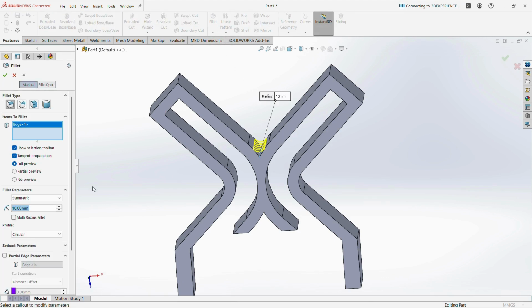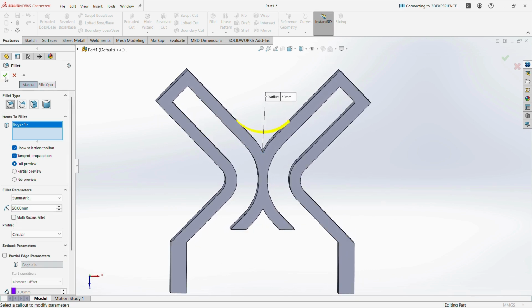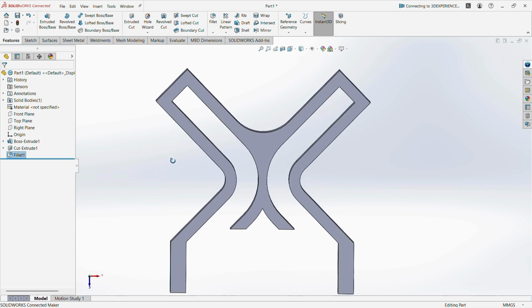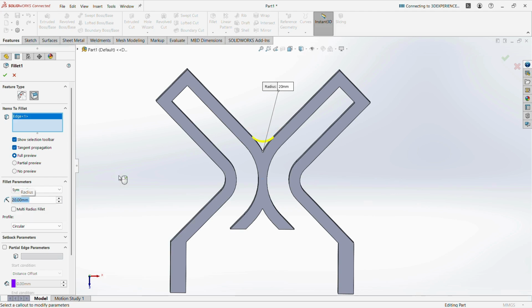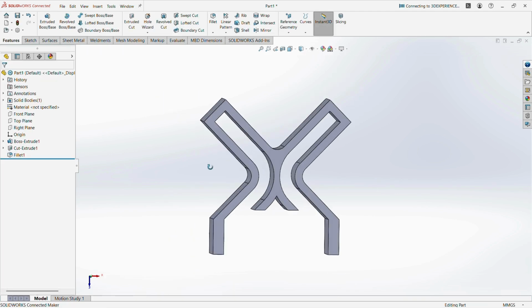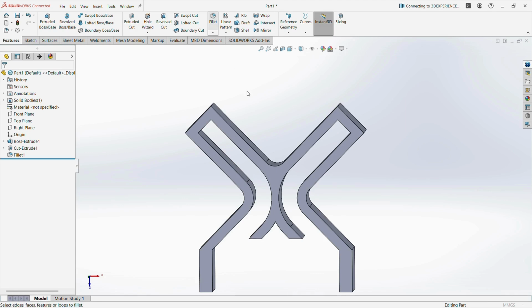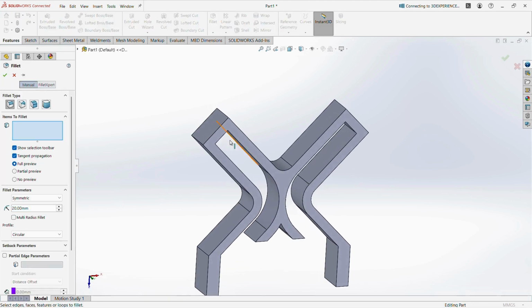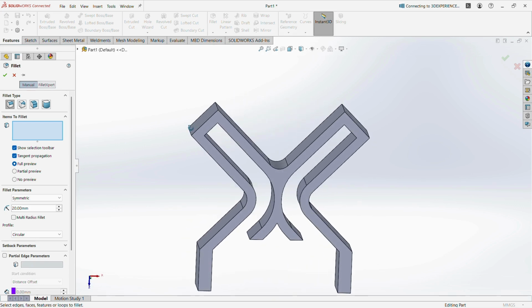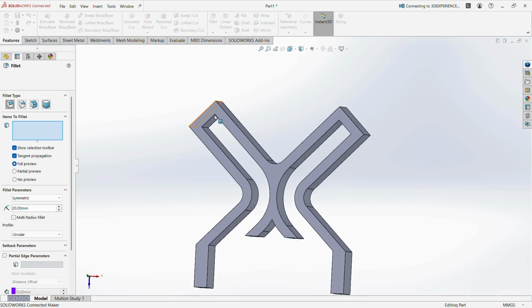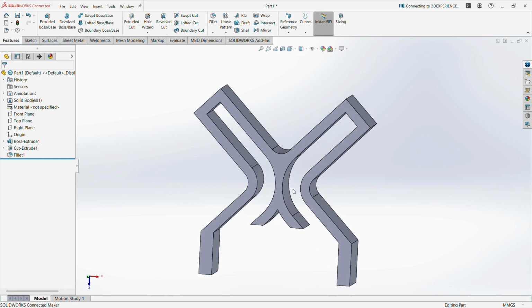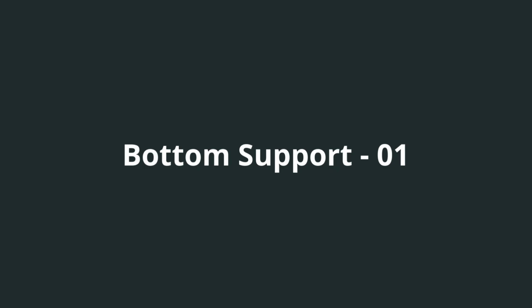Okay, now applying the fillet at the top portion. Either we can apply a 50 mm fillet or, compared to our previous one, 20 mm. From the side radius, apply the same kind of radius at the top one also. So choose this fillet feature, edit it and initiate the same value of 20 mm. Once it is completely formed, now the primary main frame is designed. Either you can apply a fillet at the corner portion or you can simply position this particular feature into it.